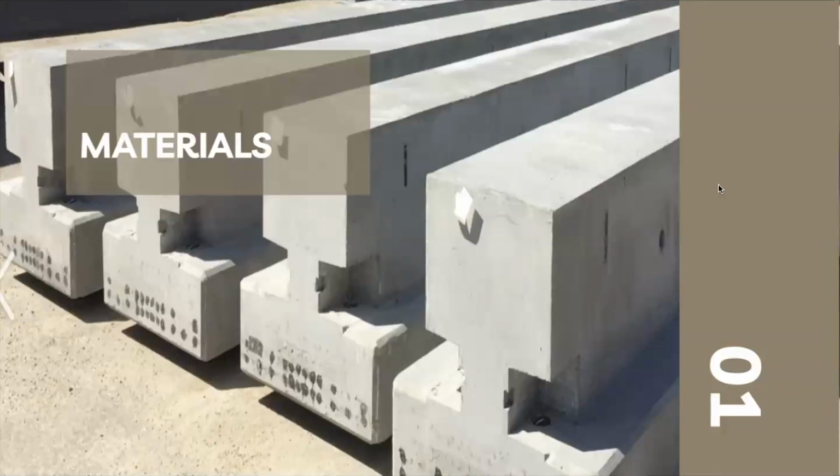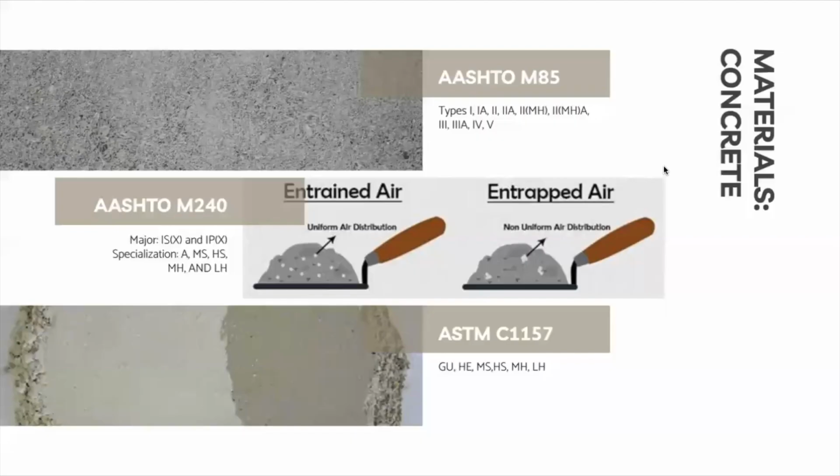Materials include concrete, grout, pre-stressing steel, post-tensioning, mild or non-pre-stressed reinforcement, and fiber reinforced polymers. Concrete composition relies on one of three cement categories: AASHTO M85, M240, or ASTM C1157.